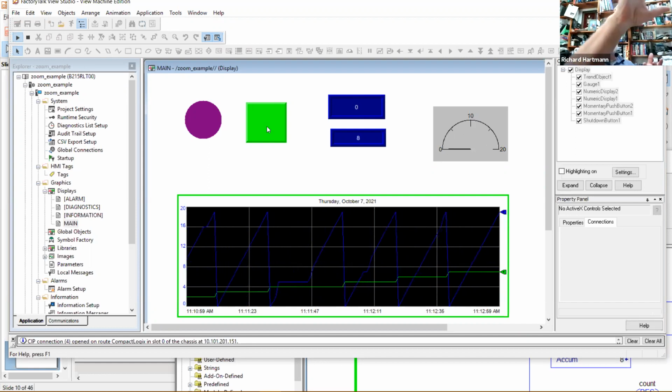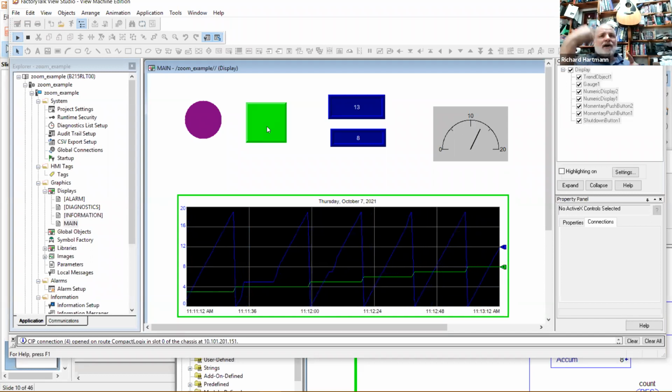So there can be a time delay between the HMI numbers and adjustments to where they get sent to the PLC. Okay. But the PLC itself is continuously reading all the inputs, calculating the outputs and responding to that. And so it may take a few seconds for the HMI to actually send a change over to it. But that's not considered time critical.